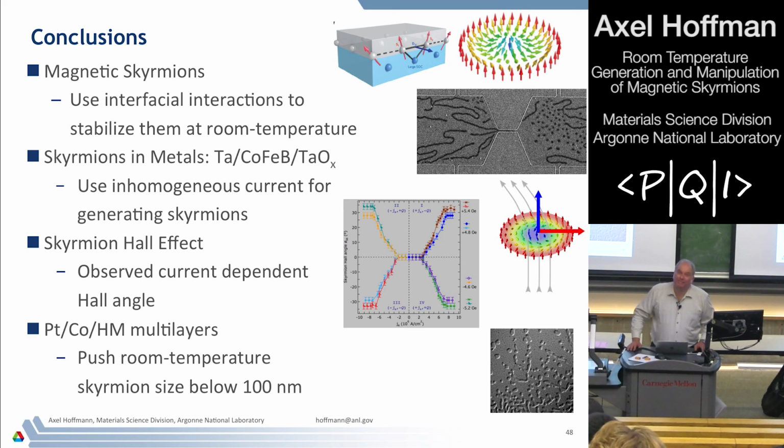Following Sarah's question, so to achieve similar orders of magnitude of the skyrmion velocity, we actually need similar magnitude of current density? Yeah, so certainly for all the systems investigated so far, that is true. We are mostly limited in the speed by the size of our devices and the resistivity of our films, and the voltage that we get out of our pulse generator.